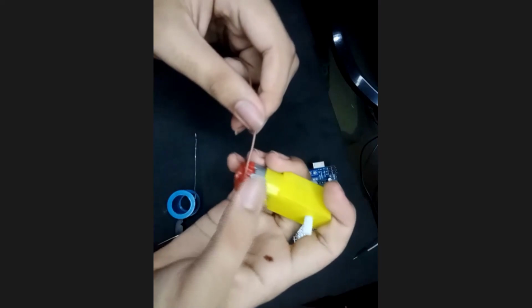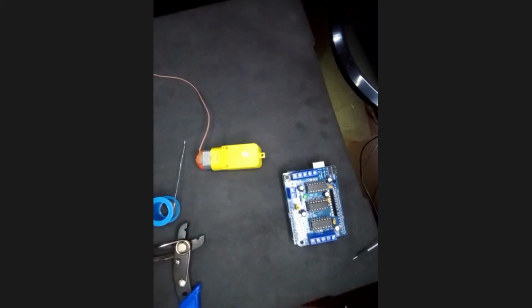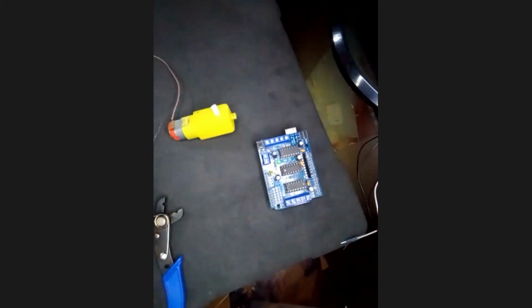Yeah, that's it. You basically just want to attach it very loosely. I prefer soldering with my right hand because I have more control over there. I'll be pulling this towards this side because I don't have that much wire. Okay, so what you guys don't want to do is put your soldering iron on the wire. You want to put the wire on your soldering iron.